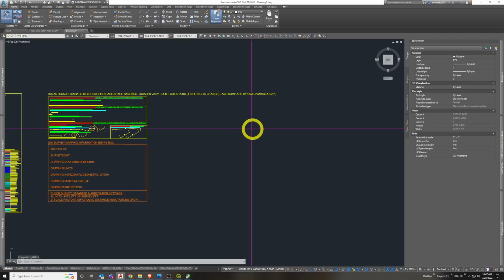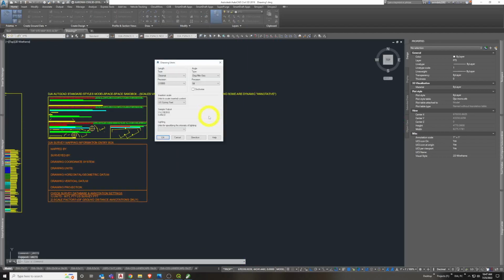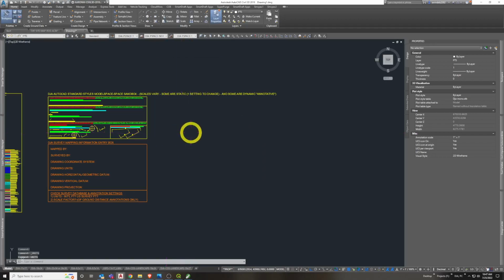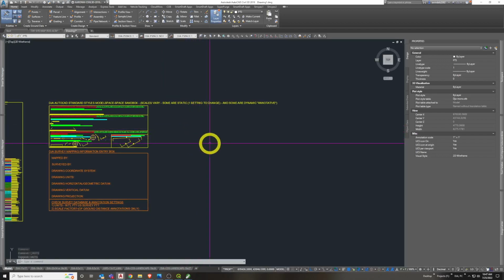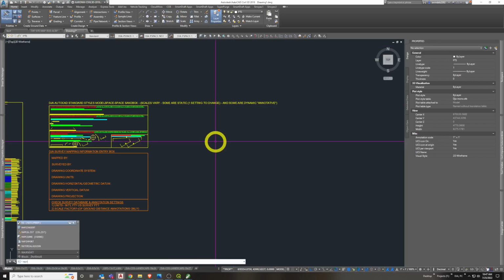So we're going to import this image. In this case, we're in Montana, so this needs to be international feet. That's potentially something that will need to be changed in the template soon because we're going to use only international feet across the US. Next step is, I don't have it in my menu bar at this time, but the alias for the command is map I insert. So 2 I's in a row.